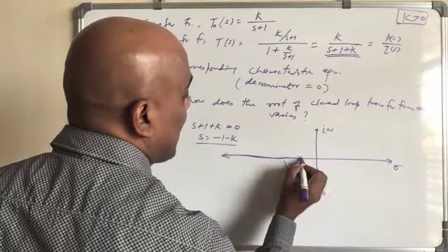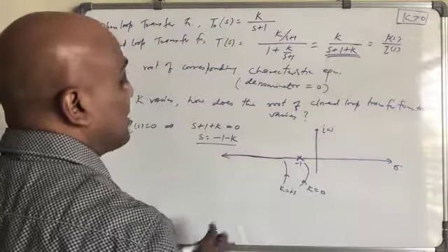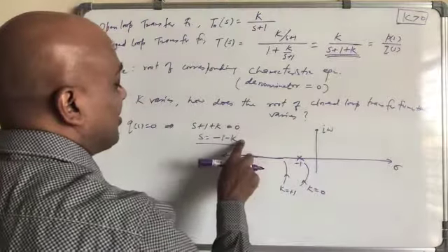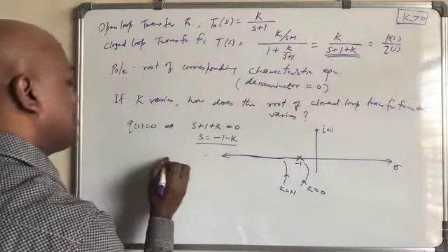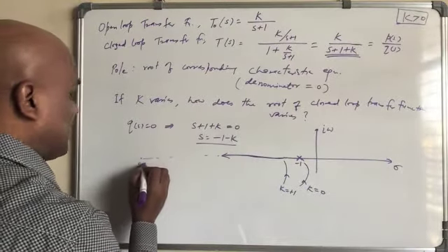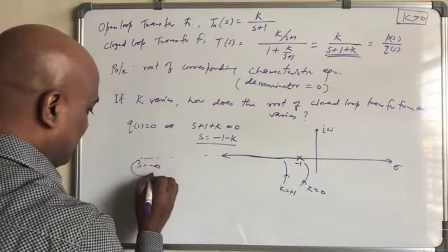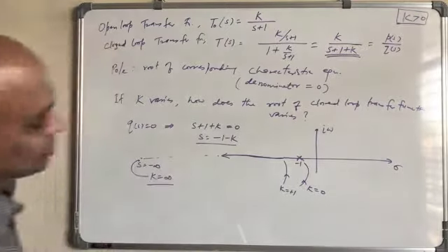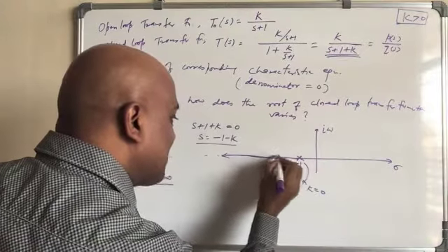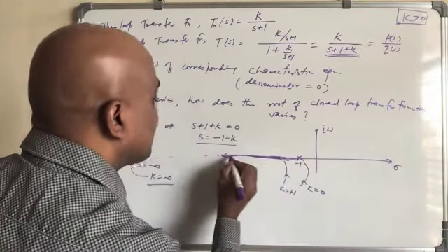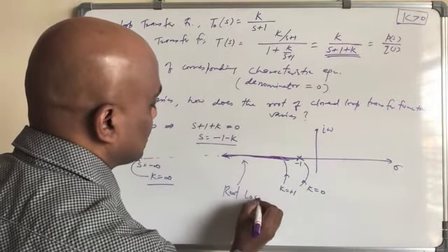It will start at s equal to -1 and it will go toward infinity. When K equal to infinity, s is also minus infinity. So go here, s equal to minus infinity, which corresponds to K equal to infinity. So this, whatever we have drawn, is nothing but what is known as the root locus. So this is the root locus.